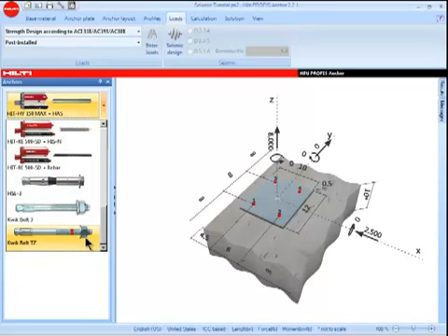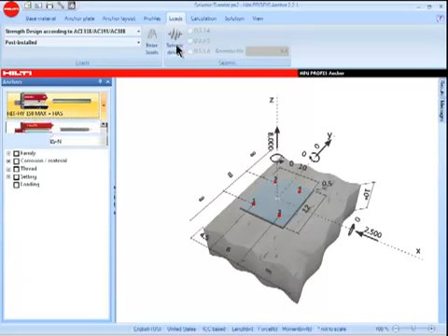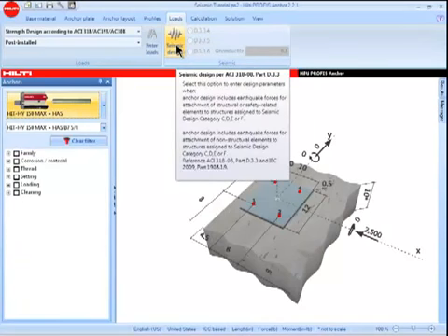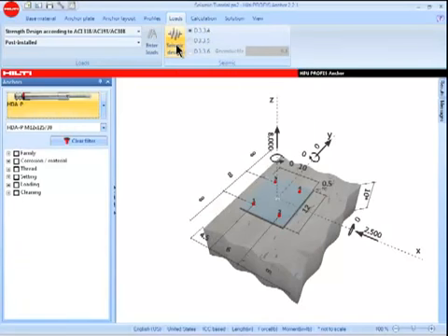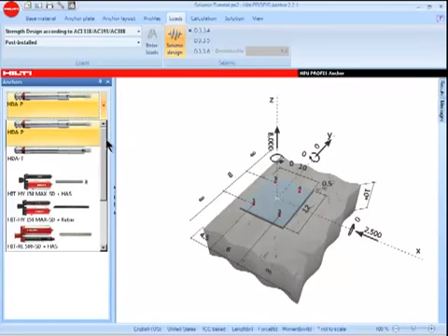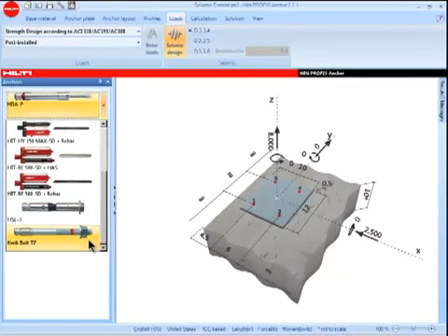The Quick Bolt TZ anchor has been qualified for use in both cracked and uncracked concrete, seismic and non-seismic load conditions. When seismic design is selected as an option, PROFIS Anchor will filter out those anchors that have not been qualified per the provisions of D.3.3.2. Therefore, note now that only the Quick Bolt TZ anchor remains as an anchoring option when we've selected seismic.